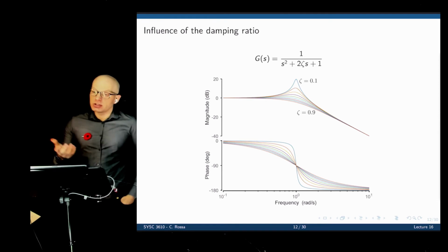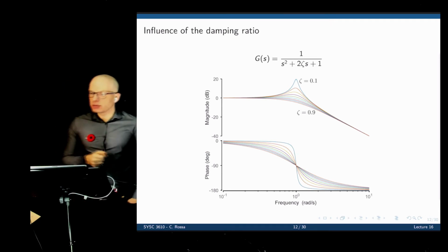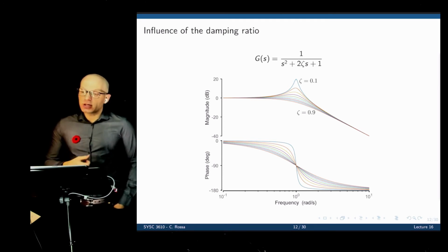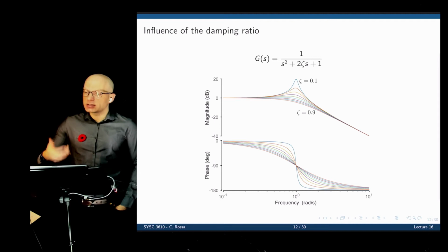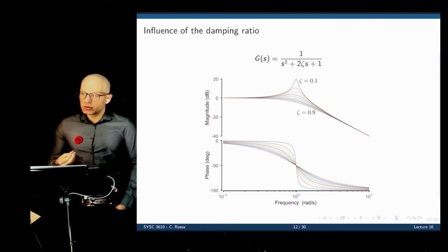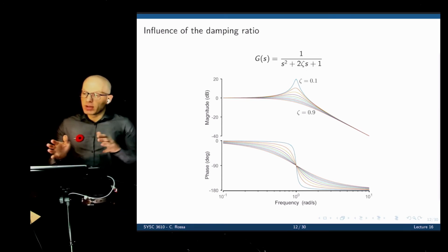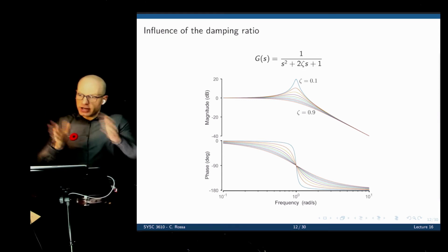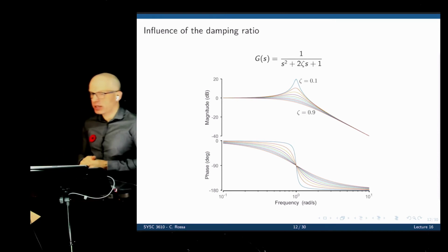And there is another example where wind just destroyed a bridge. You can go to YouTube and just type resonance frequency of a bridge, and you see a very long bridge that collapsed because of wind, not because of the speed or the intensity of the wind, but because the wind created an input excitation that was too close to the resonance frequency of that bridge. So the wind was some sort of cyclic input, and the frequency of the wind displacement induced in the bridge was too close to its resonance frequency. So the resulting displacement of the bridge was a lot higher than what we would give as an input, and the bridge eventually collapsed. You can see the video online. This is black and white, an old one.